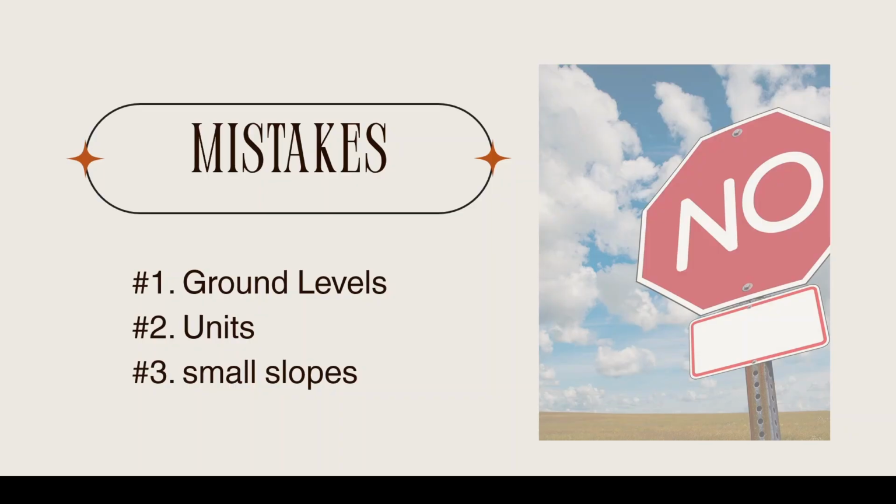And there are some practical engineering tips that we normally adopt while designing for our slope, like typical minimum slopes for small pipes normally ranging from 0.5 to 2%. Then for storm drains, it ranges from 0.3% to 1%. But the most important thing is to make sure you always check design standards as your reference point to guide you on how best you can size the system. But we should know that our slope must ensure adequate velocity and self-cleaning flow.